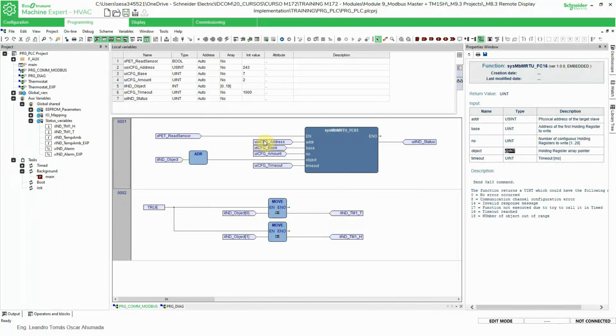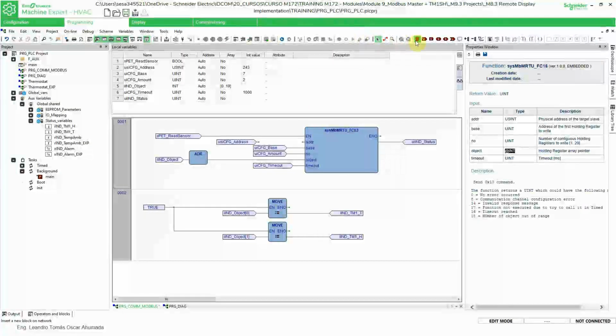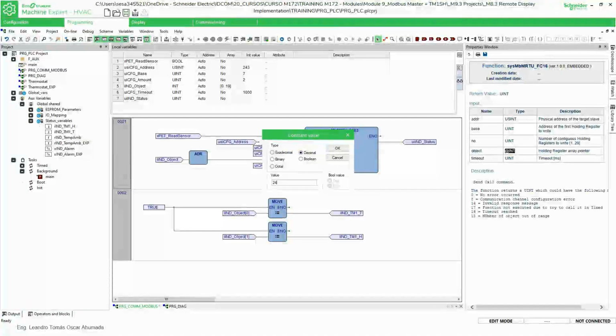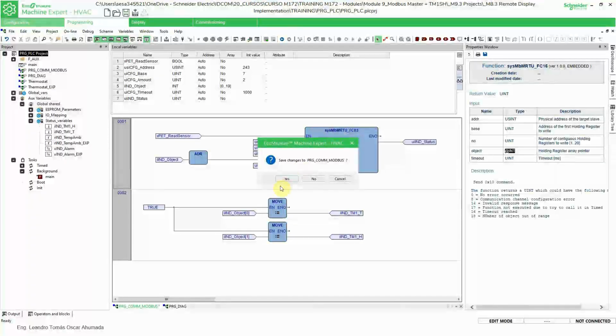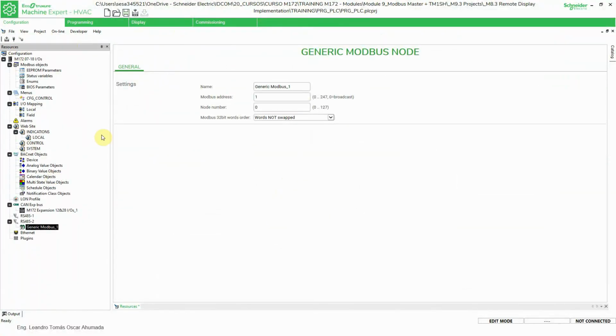As you can see here, I link the address to a variable, but I can just easily do this, okay? Create a constant and link it to the address. Okay, I don't change that, but in this particular case, I have used a variable, so I can easily change the address of the equipment and get the information. But let's go to this way, as we call the scanner way, the Modbus Serial scanner.